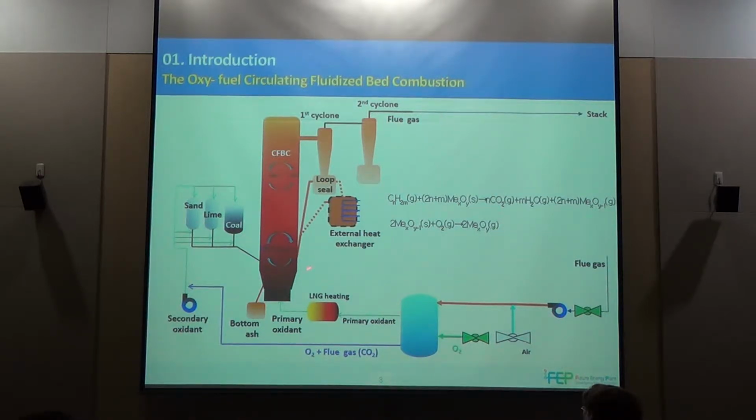Another advantage when we apply oxygen carrier in circulating fluid combustion system is that oxygen carrier will mix well in the combustor, so we improve combustion efficiency, and then we would like to reduce incomplete combustion. CO in flue gas will reduce the temperature in the cyclone. And the final purpose, we would like to consider reducing pure oxygen from air separation units.